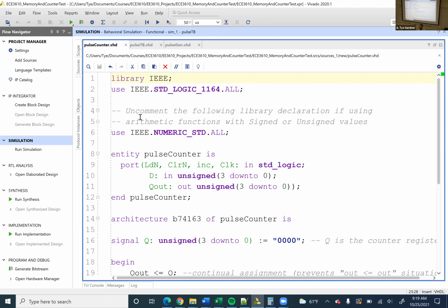So like, say you were going to build a data acquisition system and you were getting signals back from an ADC. And you wanted to send them in packets over, say, USB, right? Because a USB packet has several, I can't remember the size actually right now, but several hundred kilobytes at least worth of data that one USB packet can save. But you don't want to send more USB packets than you need. So you would just count how many samples that you received, start queuing them up in the register, right? We talked about shift registers a little bit last time. Queue those up, and then once you've counted however many samples you have, then you could send them off over USB.